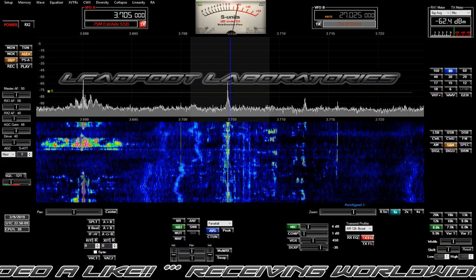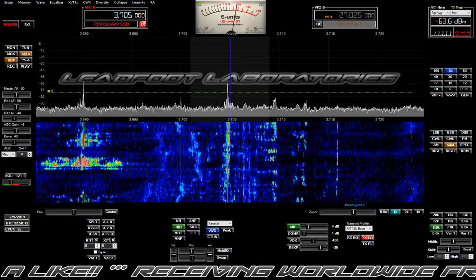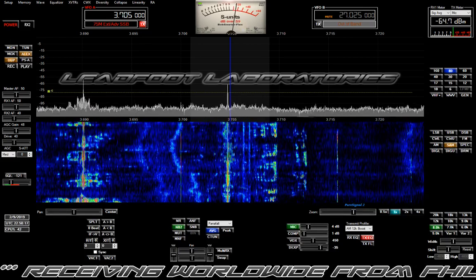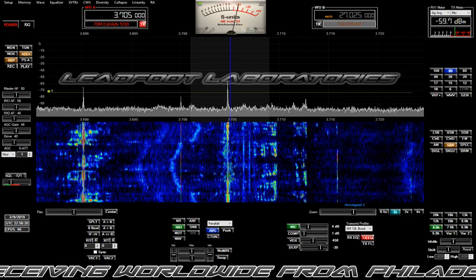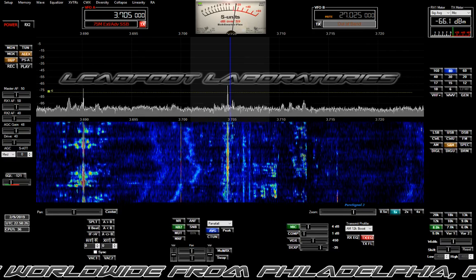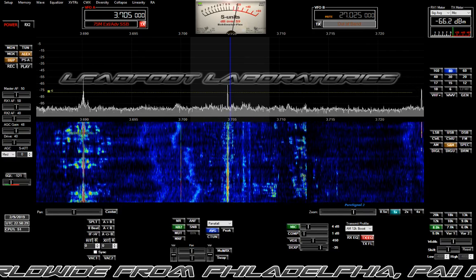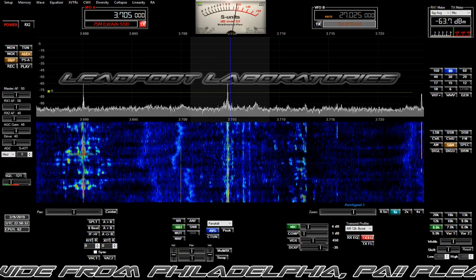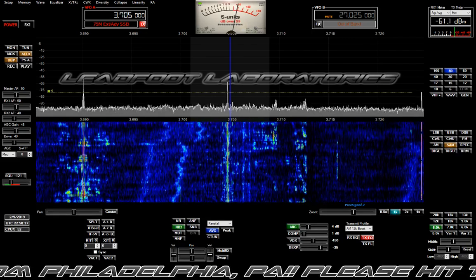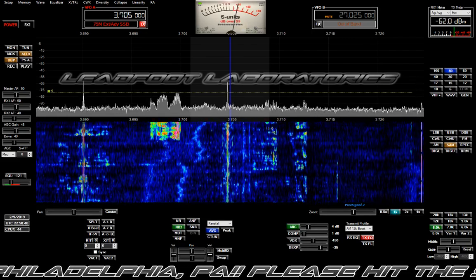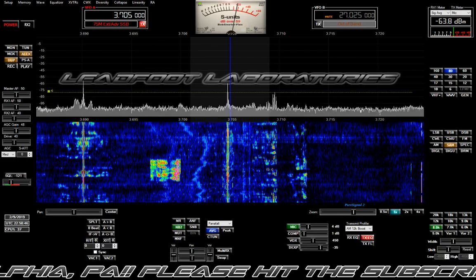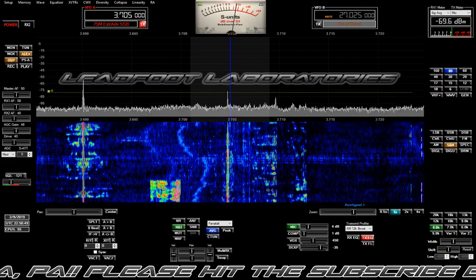They put up 2 towers to null the signal down to the equivalent of what would be a 50 kilowatt signal in Canada, and that solved the problem. But that was where they started to develop directional arrays, because you're right that the station in Florida was interfering with another station, and at the time all the stations were non-directional, so they started playing around with directional arrays, and there you have it.